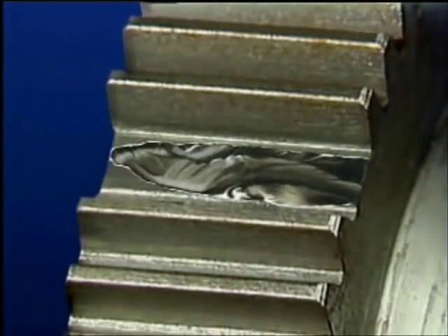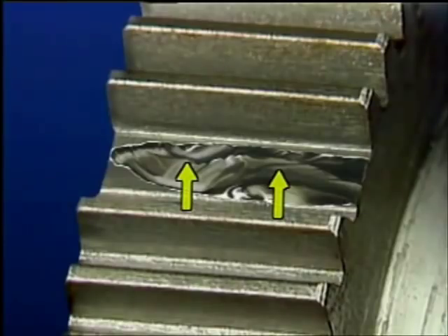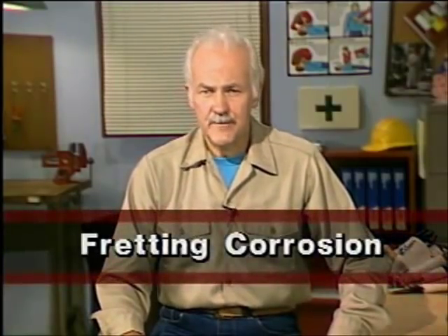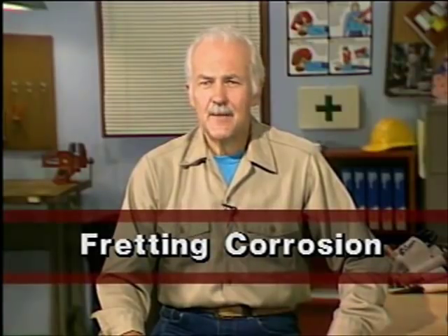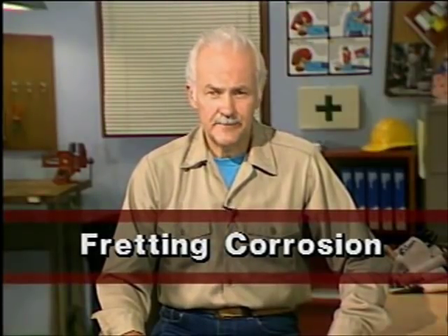When a gear tooth breaks due to fatigue failure, the appearance of the break will usually contain a circular pattern in the metal called an eye. During fatigue failure, a break slowly works its way across the tooth, and when the pressure gets to be too much, the tooth breaks off. Fatigue failures of gear teeth usually occur over a lengthy period of time, and they may be accompanied by what's called fretting corrosion. Fretting corrosion is set up as the gear tooth is loaded and unloaded.